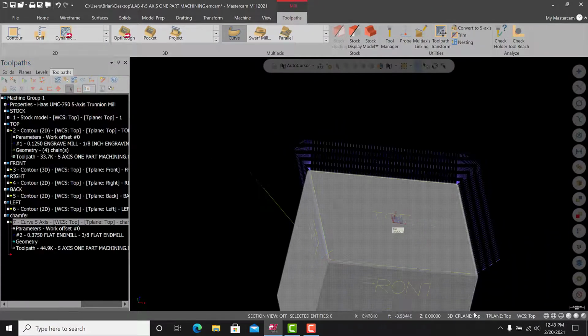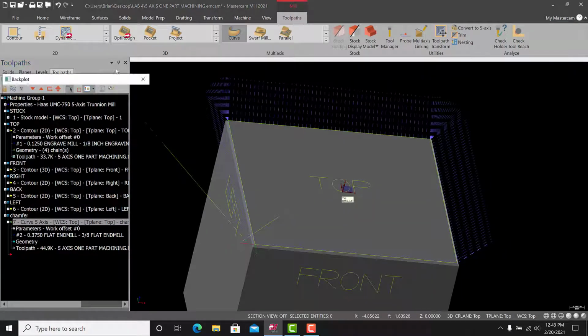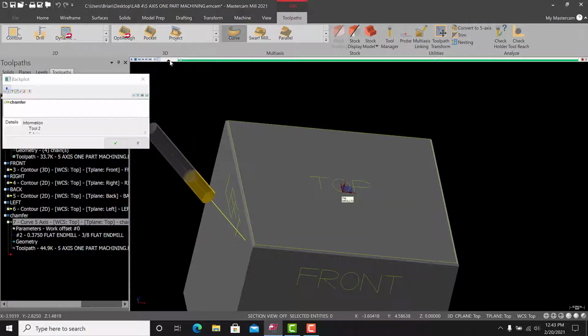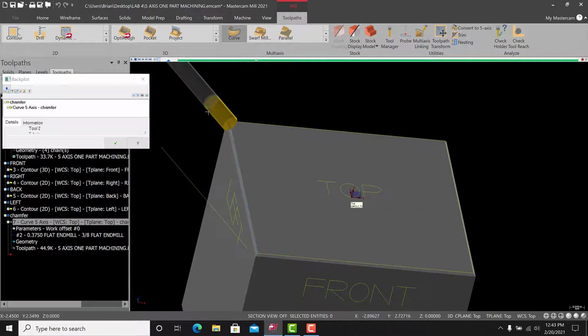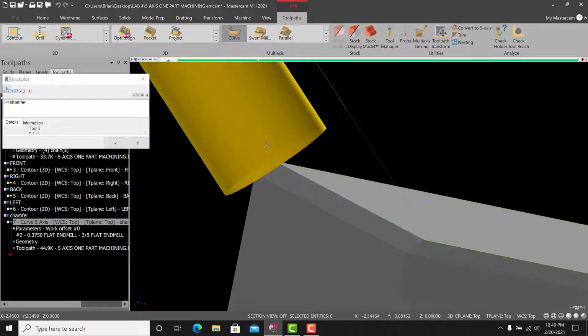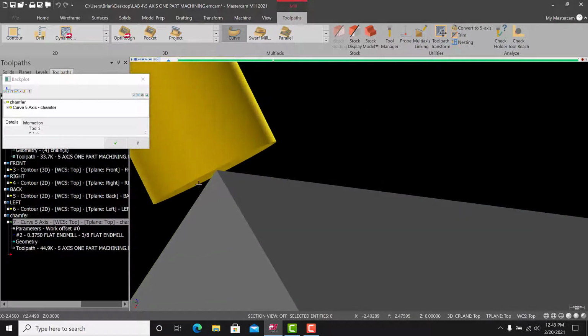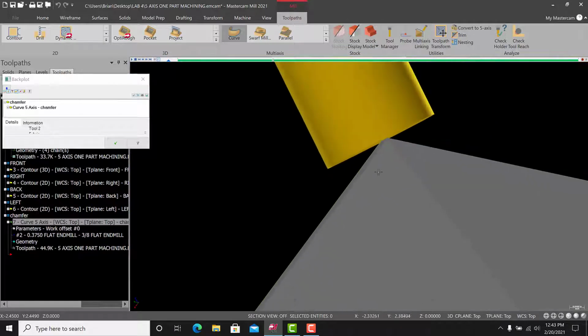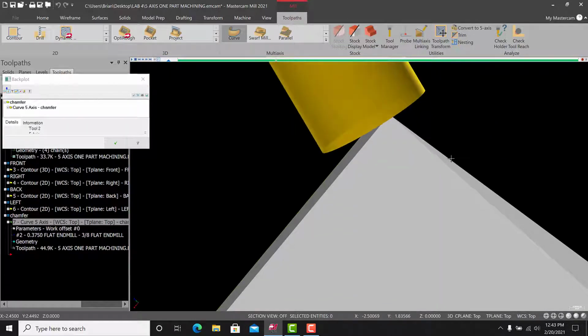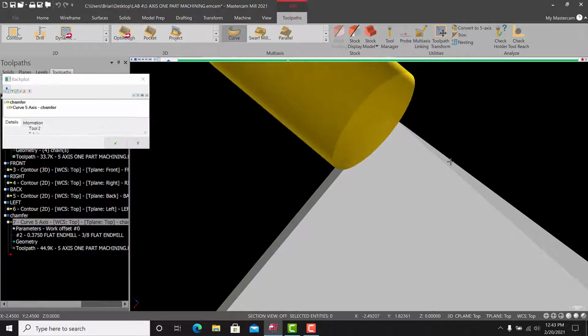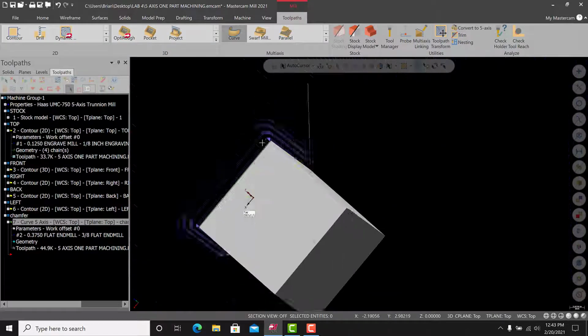We'll regen. And again, we'll backplot. And watch this run. Now, one thing you could do, you could hit stop, and I'll show you this. This is the only time I use this. If you hit S, it'll skip to the next area. So I'm clicking S on the keyboard right now, and you'll see we can watch it tilt around here. See the tilt? So we get over here and hit S, and you can watch it pivot. And that's how you know you're pivoting correctly. Okay, so I'm hitting S, and that's just single blocking around. Okay, so that looks okay.